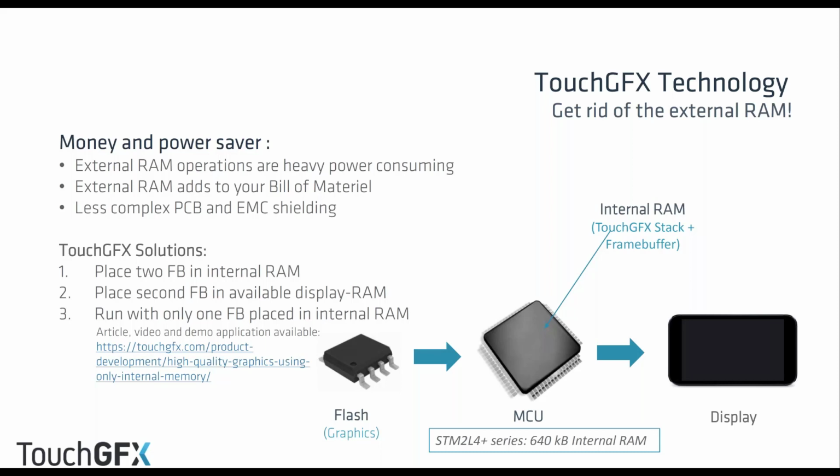And this is the setup we have on the ST Discovery Kit with a new L4 Plus device, having one frame buffer in internal RAM and the second frame buffer placed in the RAM of the display. But with the TouchGFX technology, you will actually be capable of running with only one frame buffer and place this in internal RAM. You can still have a really nice looking smartphone UI. There are some limitations, but you can go to the link here in this slide and read a little bit about this, get access to video and code examples.